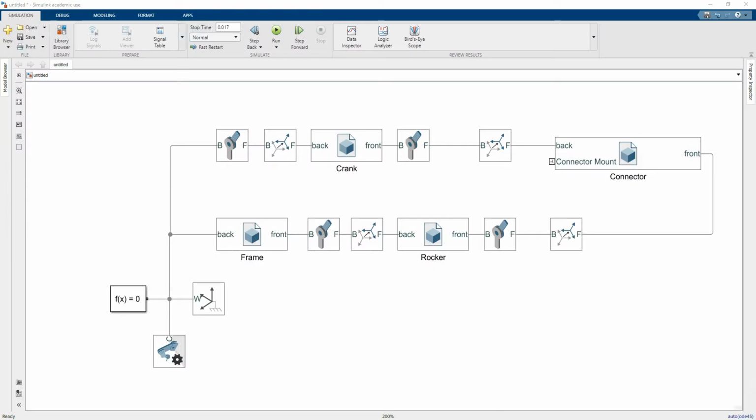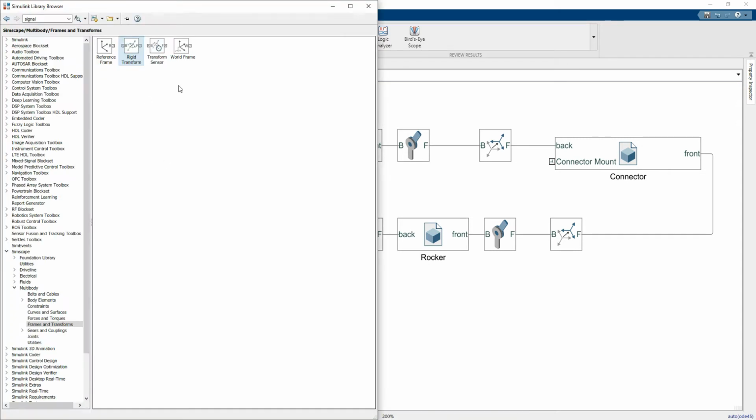Nice. So let's bring this back, and now let's start trying to mess it up a little bit, because a lot of these things are really great, but what's important with this is to be able to apply forces to it. We want to look at what's really going on. So first things first, I'm going to apply a tool that we've not really touched yet. I'm going to go to forces and torques, and what I'm actually after is external force, unless they've renamed it. No, they haven't. External force and torque. I'm going to drag that in.